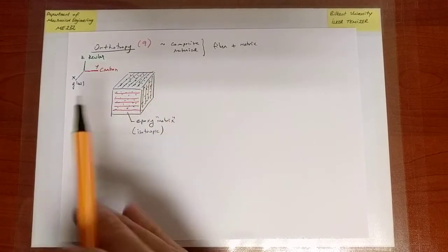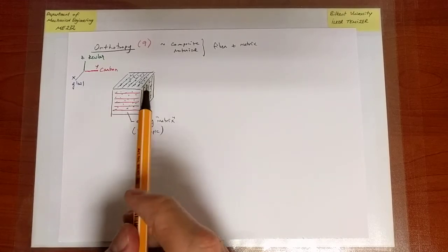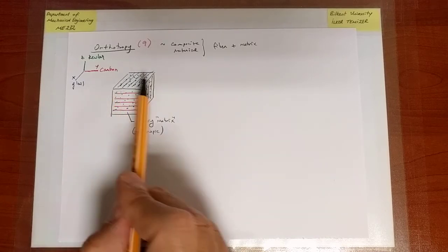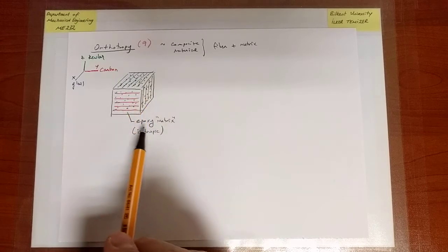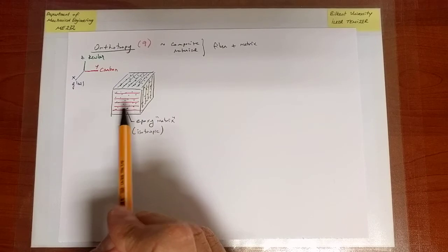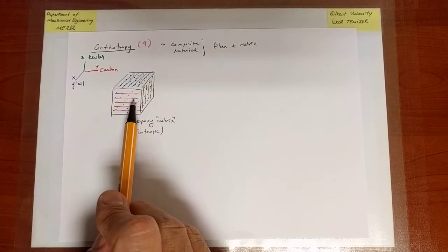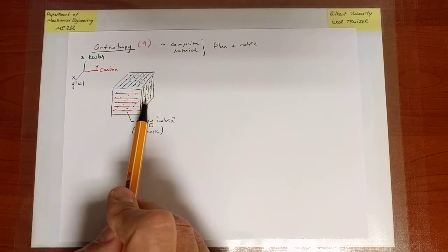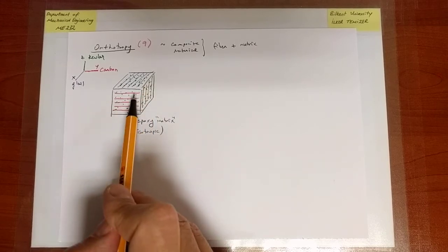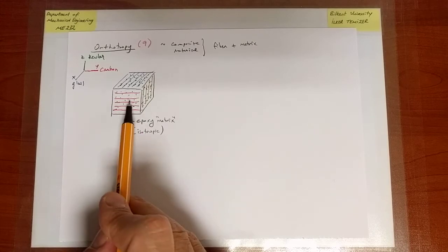Okay. So now we have X, Y, Z axes, and I'm just wondering how I can characterize this material. I'm only interested in the elastic behavior. Now I can already see perhaps that the strength along each direction is different, and each is different from the original strength of the epoxy and also of the fibers. And the same thing goes for elastic properties, but here we're only concentrating on elastic materials. So likewise, the Young's modulus along that direction is going to be probably different from that and different from that, all of which differ from the Young's modulus of the epoxy matrix and of the fibers themselves.